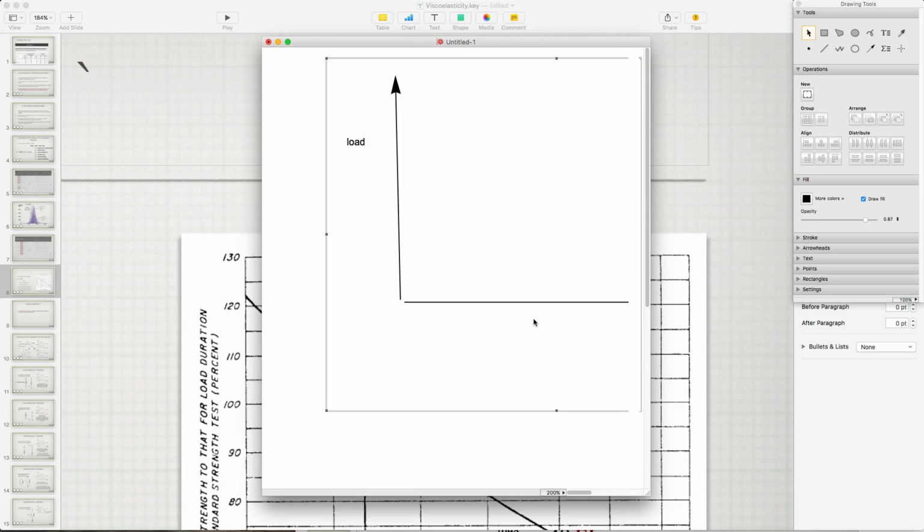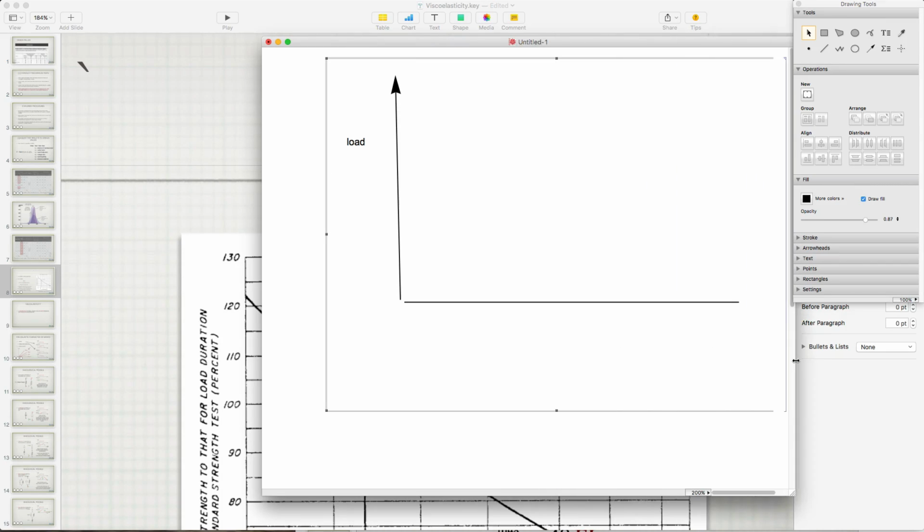And we'll call the horizontal axis time. Now let's say I'm designing and it's the design codes that are provided by the government that says if you build a house, you shall design and expect that there is a 40 pound per square foot live load. How they get that, that's a whole other story, but you are required legally to design for that condition.